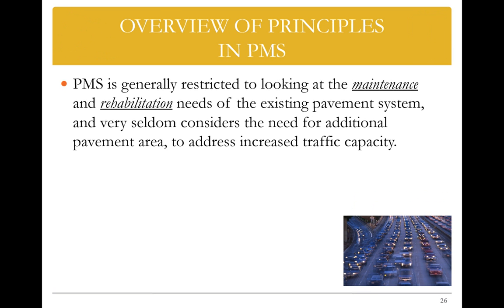Another point that I want to point out here is that the pavement management system is generally restricted to looking at the maintenance and rehabilitation needs for the existing pavement system. It very seldom considers the need for additional pavement area to address increased traffic capacity. So this is a totally different thing. When we look at the pavement management system, it is about how to maintain and rehabilitate the roads.